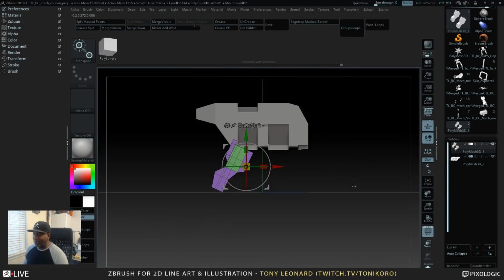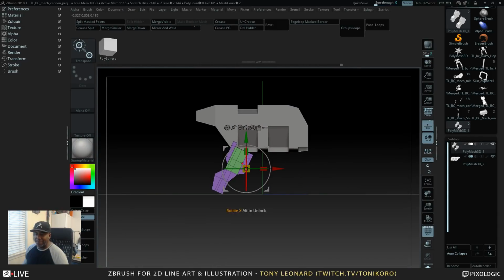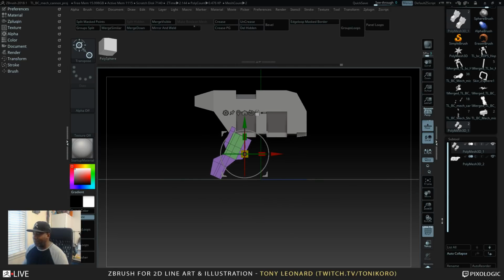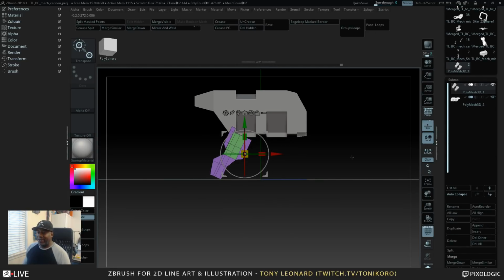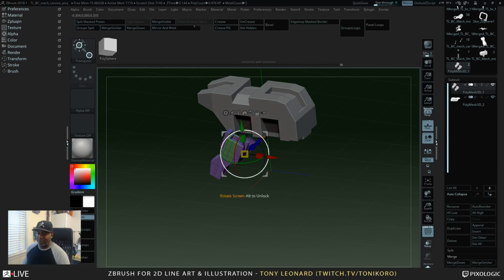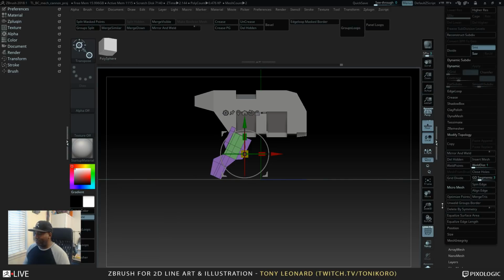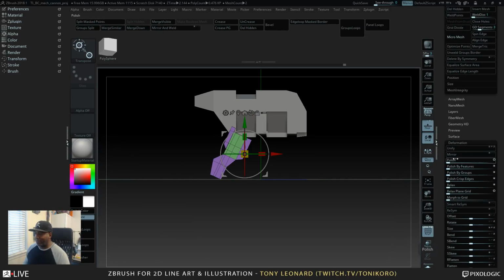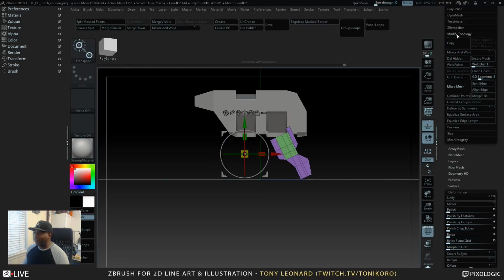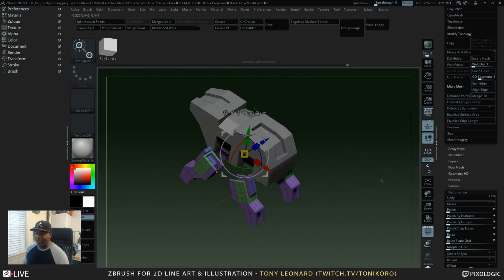But first I'm gonna actually mirror these along the front axis, the Z forward axis. Because this line, of course, would be Z forward. This would be towards the back. So I'm actually going to just mirror this really quick and then mirror it back. So I'll mirror it along the Z, turning off X and Y. Mirror it. And then I can come back up to modify topology and just do a Z forward again and mirror and weld here. So now I have that back pair, right?